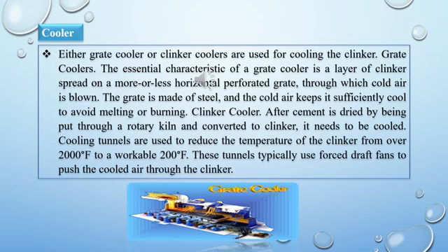As the cement passes through the kiln, because it is heated there, it is now necessary to cool down your cement. And the next equipments are coolers. Either grate coolers or crinkle coolers are used for cooling clinker.